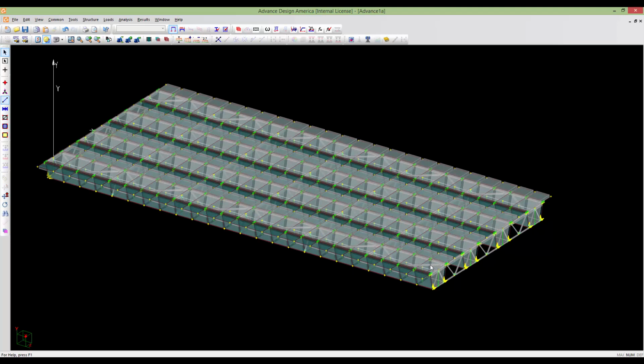Also, to design these members, the top braces here, we are going to assign them a continuous lateral support. You can again define a selection for these members. Okay, I can mask them.